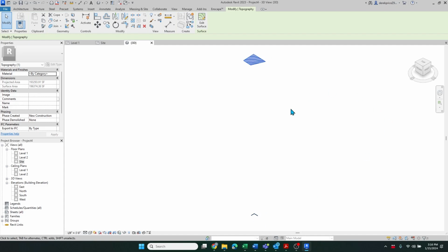Okay, so what I want to do is fix my coordinates. I want to adjust my coordinates to work with where my TopoSurf is. Let's say you've already modeled something on here and then you fix your coordinates later. Then instead of trying to grab the model and the TopoSurf and bringing it down to this elevation, it's better just to adjust your coordinates to bring up to what you've already done your model at. Otherwise, you're going to get lots of errors.